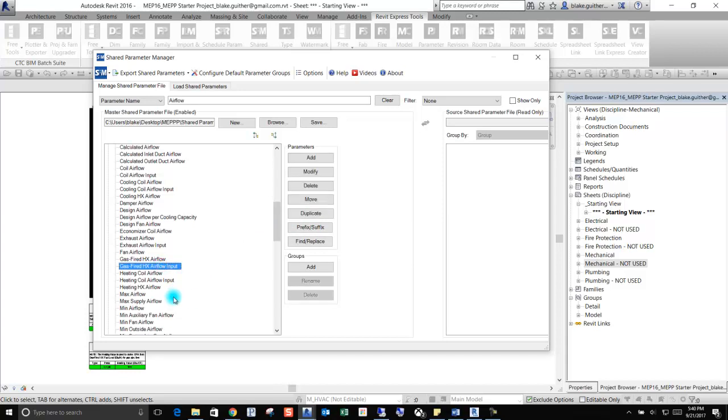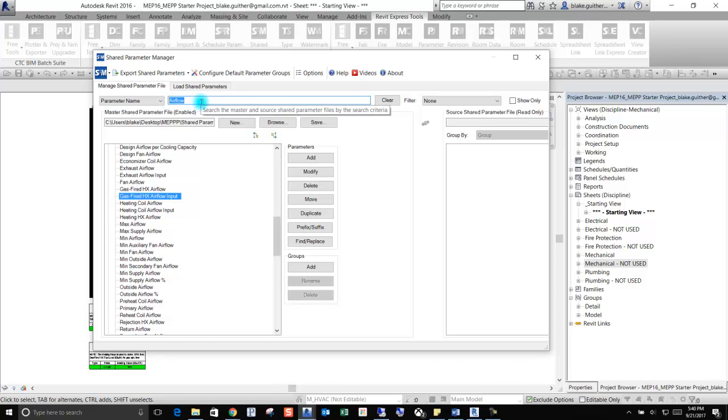So this set of shared parameters includes functionality for auto sizing across many families with calculations for electrical, for mechanical, from the connectors, not from the connectors, all of that stuff. So that needs to be taken into account. As you can see, some of these input parameters function as overrides in some of our equations.